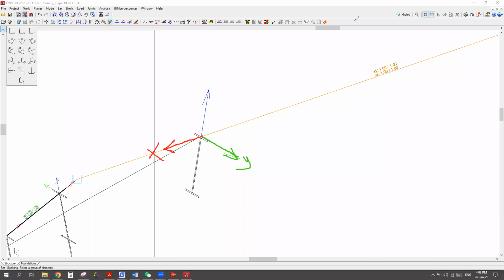And the last one here is the Z-axis. In STAAD.Pro, the places of Y and Z are opposite: here you have the Z-axis and here you have the Y-axis. Now we have two main planes. Maybe I can go for the XY plane. So this is the XY plane.